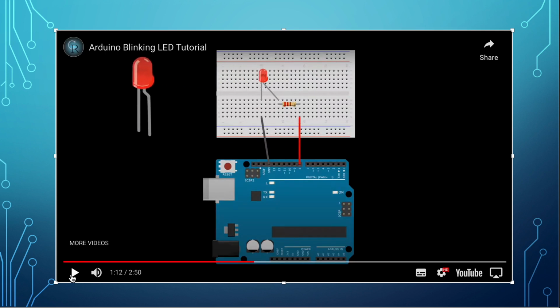So okay, now we have a connection made. From the Arduino, you can see which ports are being used right here. They have used the ground, and they have used port number 8 for this connection. As you know, if this wire is connected to this line, it is connected to anything which is also fixed to this line, so that means the resistor.